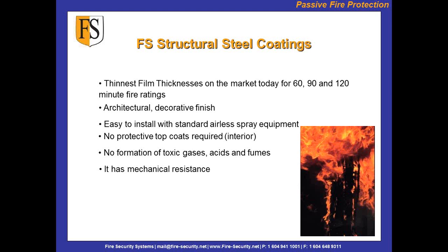for. So if, for instance, you came to us and you wanted a quote, we would need the fireproofing steel schedule, which is all the steel to be fireproofed, whether it's an internal or an external application, the steel itself, not only the section but the length of section, so that can give us our overall square meters, and whether you want it installed, which we'll now discuss, after erection or pre-erected.